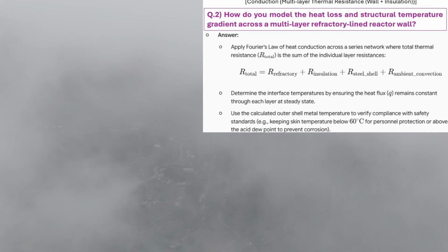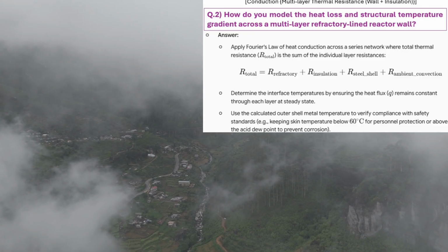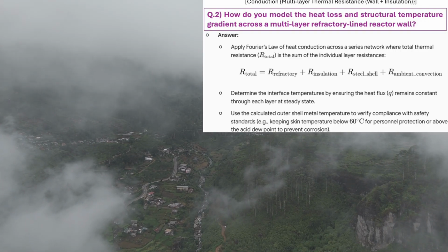And in a hydrocracker, exposing low-alloy steel to high-pressure hydrogen directly triggers what? High-temperature hydrogen attack, or HTHA. The molecular hydrogen dissociates, diffuses into the steel lattice, and reacts with the carbon to form methane gas. Which physically rips the steel apart from the inside.